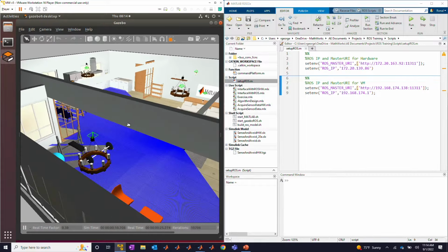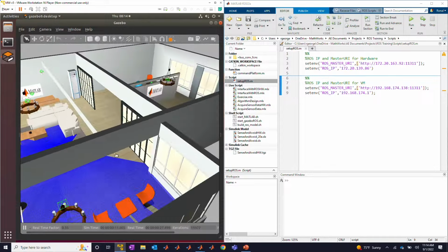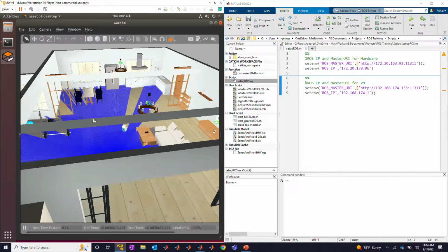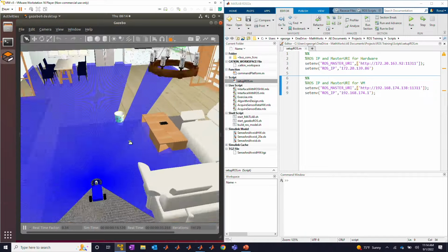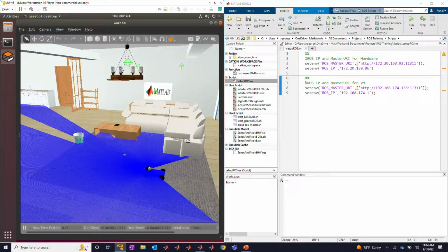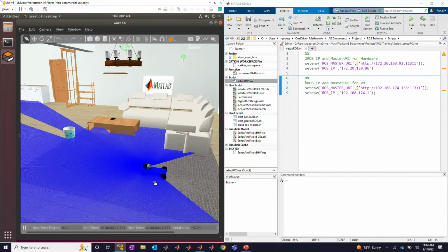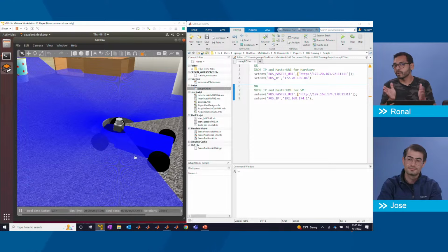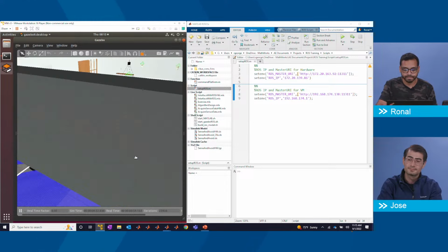So here you can see it's a really nice environment. It's got a living room, a bedroom, and a lot of different assets such as couches, a barbell if you want, and a couple other things that we've put in the environment. Now you can see that I have a robot here. It's a mock robot that I built, which is very similar to the frames of this robot. So it has the LiDAR at the right place. It has the camera at the right place. It uses an Ackermann or car-like steering model. So the front wheels will steer and the back wheels will provide acceleration or torque.